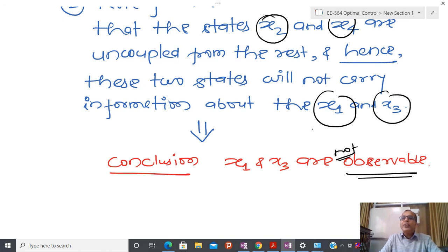And if I have a fewer number of state variables, then I have to check whether the system is observable or not in order to proceed further. Because if the system is observable, then from a fewer number of outputs I am able to understand the initial condition of all states, and then again we are able to solve the optimal control problem. And in this whole course I am going to talk about either linear time varying systems, time invariant systems, or some kind of autonomous and non-autonomous systems.